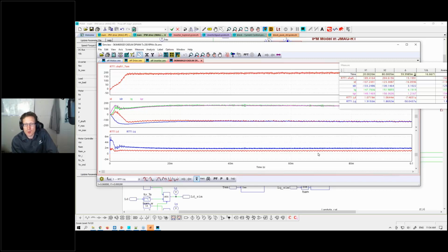Can you model rotor loss versus DC link voltage switching? Yes, of course we can. This is a working motor drive. This is a working inverter. So if we change the DC link voltage, we could run all these simulations all over again with changing DC link voltage. If we increase the switching speed, we'll see an increase in the switching losses. All of that information is easy to see. And comparing device to device, IGBT versus silicon carbide, one manufacturer's discrete device versus a 6-pack, that all can be included.